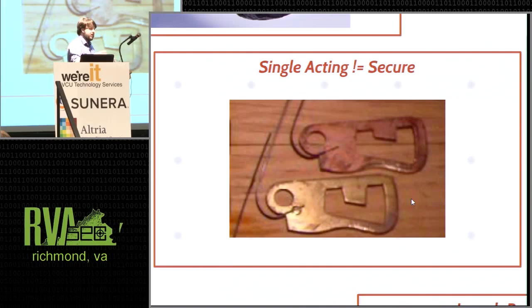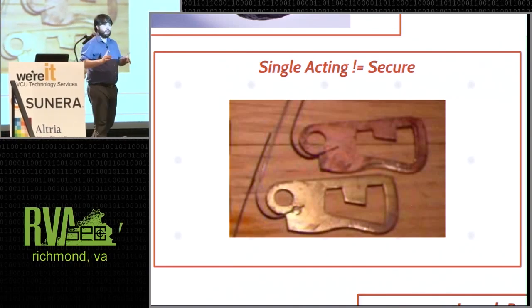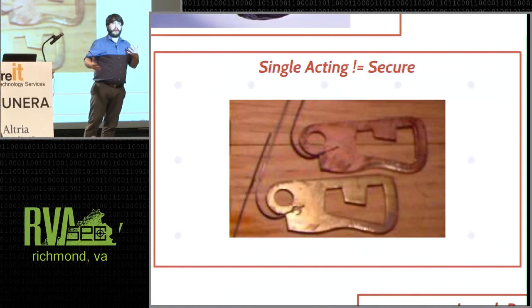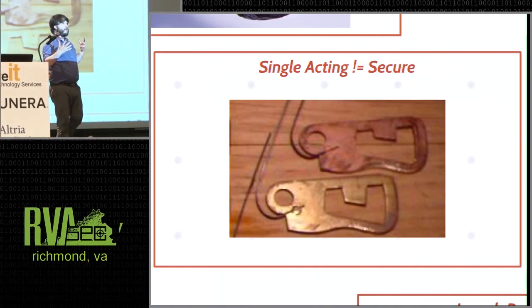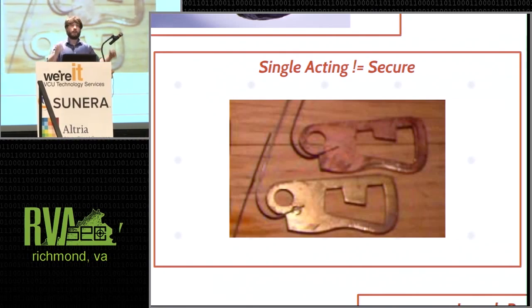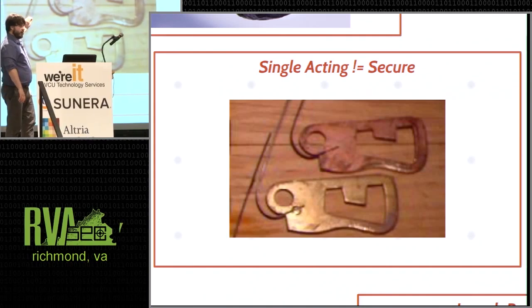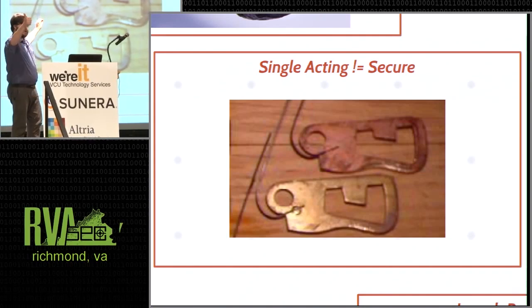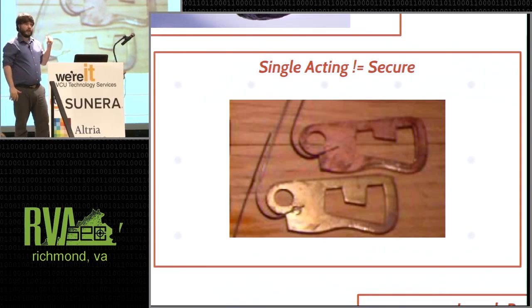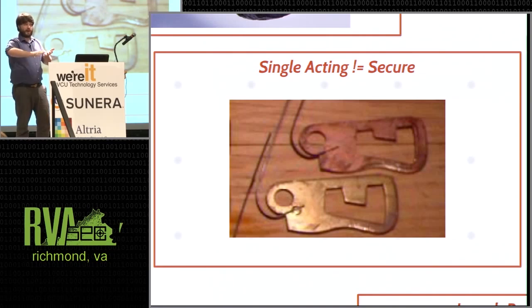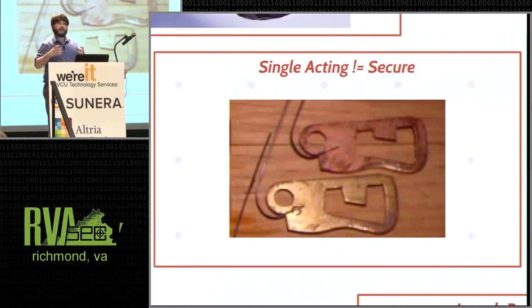All right, so that's all well and good, but a single acting, which is now what we call this type of tumbler mechanism, is terrible. Because you could just lift that lever up as high as you wanted and then manipulate the bolt back and forth. There was no upper limit on it, so you weren't lifting it up to the right height, you were just lifting it up. So we then get enclosed tumblers, where you can lift it up only so high, at which point it cuts you off. So that's cool, except that this now becomes incredibly easy to impression again. Because as soon as your key stops, remove a little material from it. See if it goes far enough, not far enough, remove a little material from it, and eventually you won't be lifting the lever up too high anymore, and the lever itself has told you exactly where the key needs to be cut to.